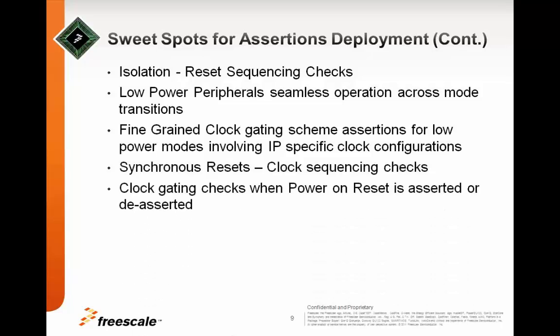The power on reset generally is not synchronized in design with the assumption that the primary clock source would be available only a few cycles after the POR is released. So if such is the case in any low power SoC design, it can again be easily checked through assertions. DVS enablement checks. It is extremely critical that the dynamic voltage scaling mode is not accidentally enabled due to an incorrect operation of any low power signal in the design. Thus, it is required to check that the DVS is enabled only when it is intended to do so.